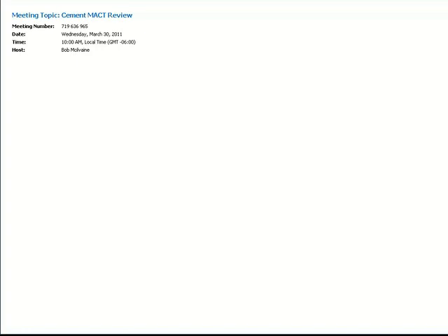Well, I don't think you'd want to measure before the scrubber to meet your particulate limit. And there are extractive light scatter monitors for wet scrubber applications. So basically my question is that there won't be any of these cement installations or utility installations that are now required to put in the PM monitors that will try to measure anywhere except at the stack, right? They're not going to be able to do it like the opacity monitors where they measure prior to the scrubber. Correct. I think all of the particulate monitoring will be done in the stack.